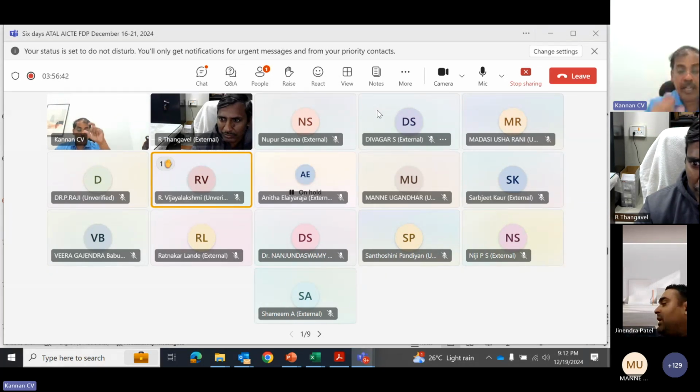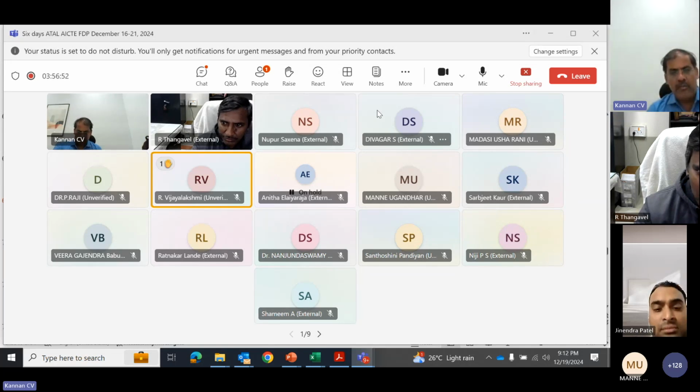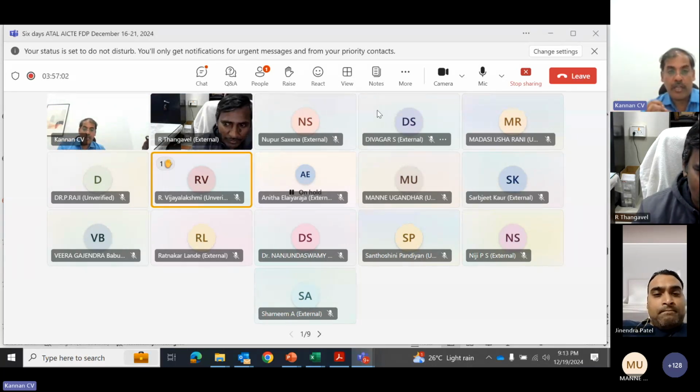Also the minority carrier lifetime you can measure. If the minority carrier lifetime is very high and iron content, carbon, everything is on the lower side, you can claim it as a high purity or electronic grade. If the minority carrier lifetime is poor and oxygen and carbon concentration is very high, you can consider it as solar grade polysilicon quality.